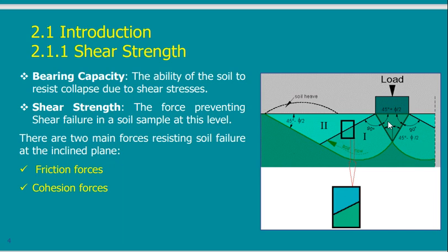So they said this triangle below the load is affected by the load. If you push something in the ground, it will push a portion of the soil below it, and this portion will be as if it is hiding below this foundation. So this small triangle, they consider that it will behave as one body. It's not going to be compressed. It will move as if it is one block. So what will happen once the load comes? This will try to penetrate, to go down.